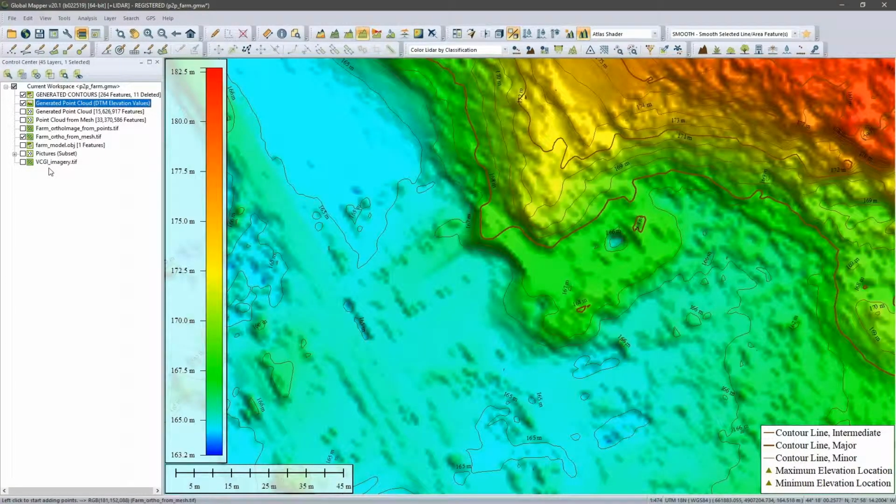Yeah, so when I created my terrain surface, I told it to interpolate across some of that data with unknown locations. And so it has done an estimation of what would be ground underneath that building. So we do have an actual, quote unquote, ground surface there, and it is actually doing the contours. This looks fairly accurate. There is actually a hillside towards the back of that building. So it's almost like you chopped the building off to ground level. Yeah, and made an assumption there. It's kind of flattened out, connecting the dots between the known locations of elevation.